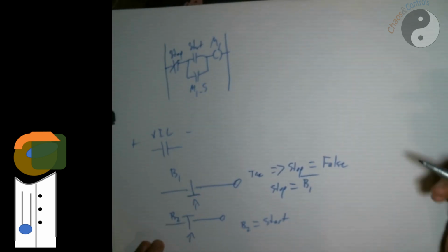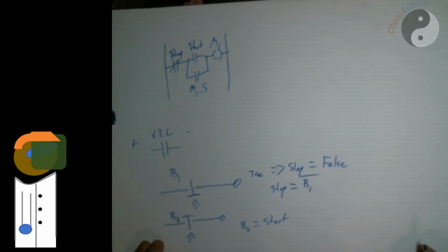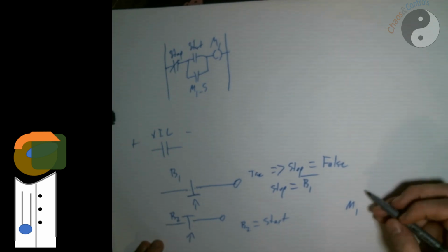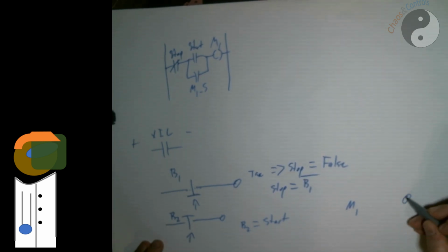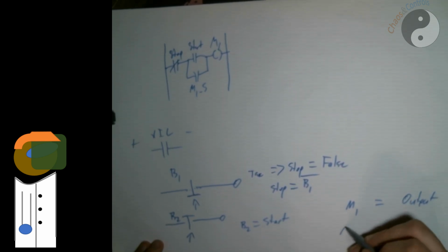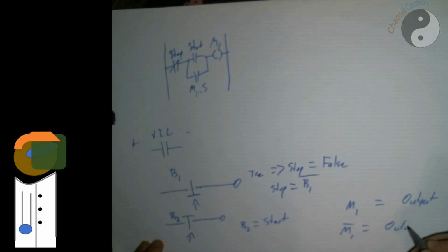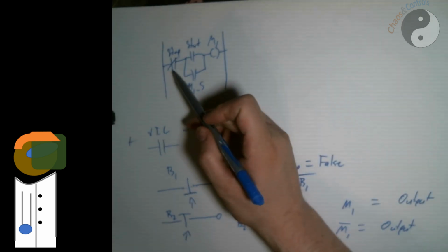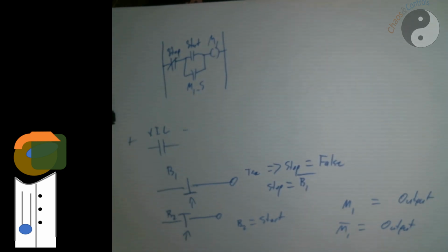And subsequently, we should also talk about, for M1 going out, maybe the motor starts off of a 0 signal, or maybe it starts off of a 1 signal. All I need to do is take my M1 status, and then I'm going to have some sort of an output block, and I either need to just set it equal to that, or M1 not is equal to that. Simple logic inversion, and then I can isolate my physical inputs from my physical outputs, and then I can use the same logic on the software side.